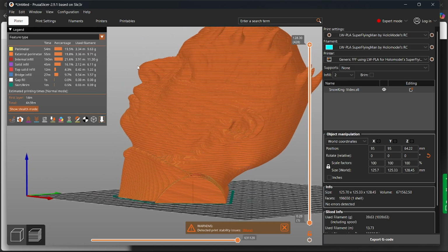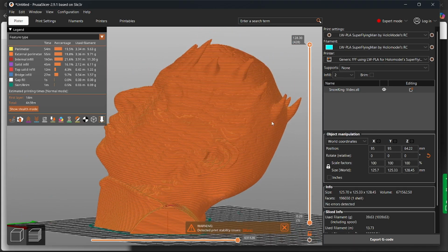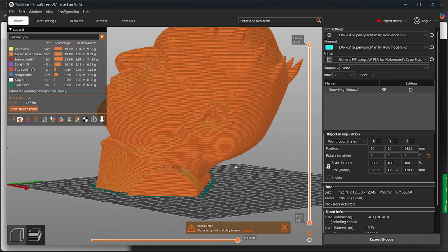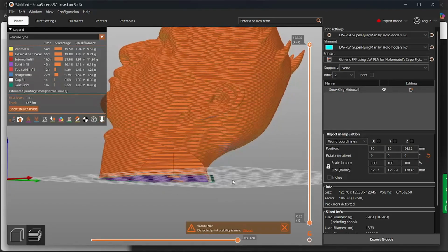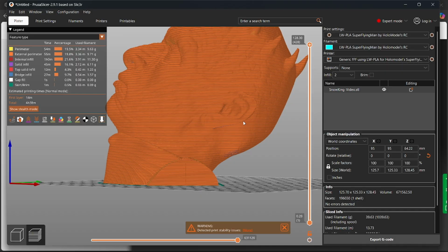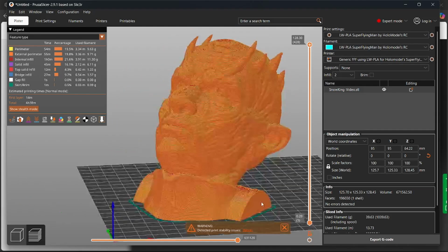And then when it gets up to like his nose, for instance, from right here up, I will print from outside in so that it can work this area a little bit better. And that's the only 2 real problem parts I see. Although the nose, it'll print fine. It'll print just about everything fine, except you'll need a lower layer height right here, and then maybe possibly in the bottom half of his ear section. Now, I will get this guy to print correctly. I'm not going to do it in this video, and I will upload it with this file and this video, so this will all be available to you.